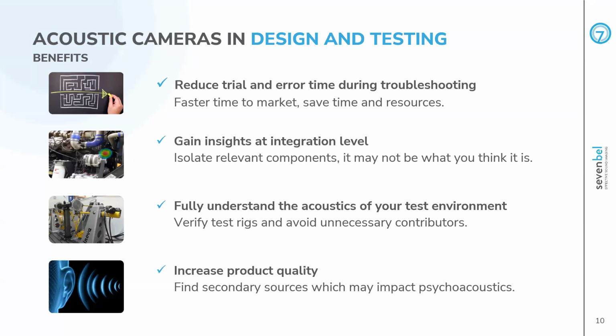Also, in many situations, things may get nasty when multiple components are integrated and they start to interact. So let us imagine you're a tier 1 supplier, for instance, and your component will be integrated into a final product. Your component may then excite certain connected structures and components. So it's not your component which is causing the noise, but it is other components that get excited at a certain frequency and emit sounds over a larger surface. So the solution may not necessarily be exchanging that supplied component, but fixing the other component so that it will be better decoupled or does not resonate that well at that given frequency.